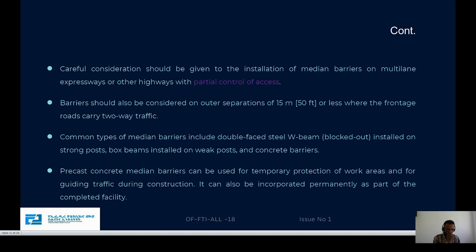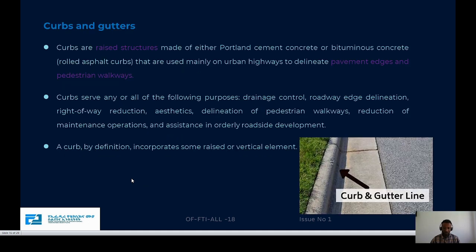The installation of a median barrier should be carefully considered, as it provides partial control of access. Common types of barriers are double face steel beams, box beams, and concrete barriers. Mostly used are the double face beams, as well as precast concrete for medians.